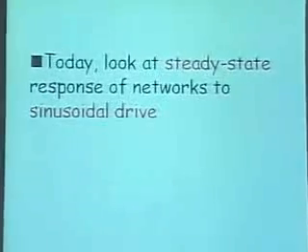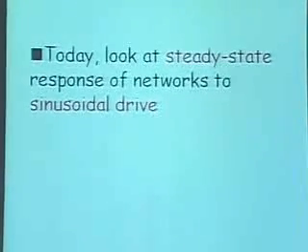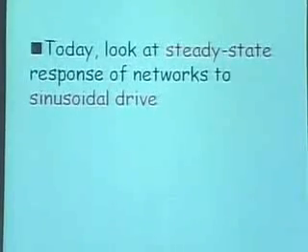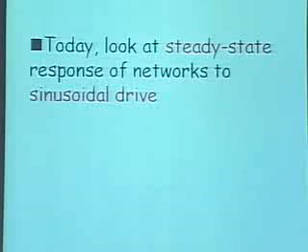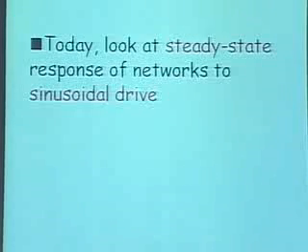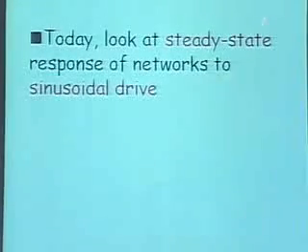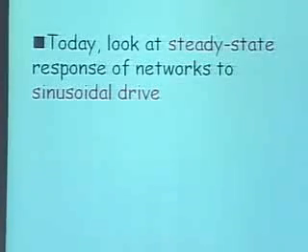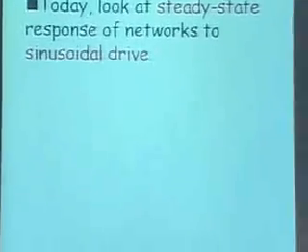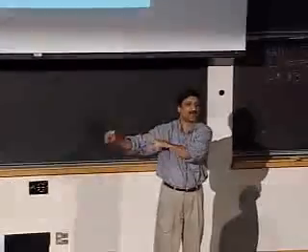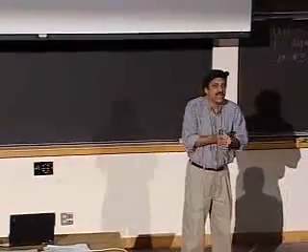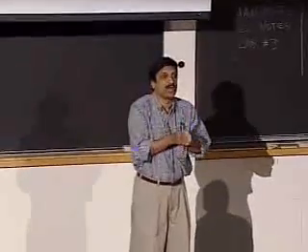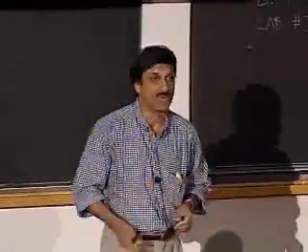So we're going to do two things differently starting today in this new journey of ours. In the past, we looked at time domain behavior of circuits. For RLC, for example, we looked at the transient response. I mean, what happened the instant I turned something on? It was a transient response. Today, we're going to look at a steady state response. Steady state response says that if I wait long enough for whatever the circuit wants to do in the beginning of life to die out, how is the circuit going to behave after a long time? I'll tell you why that's important in a second.